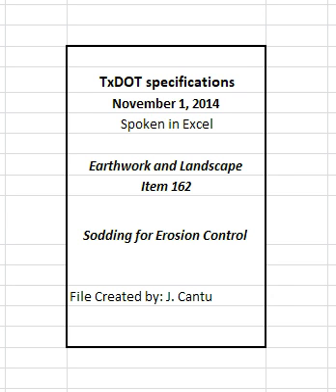3.3 Straw or hay mulch. Apply straw or hay mulch for spot sodding and mulch sodding uniformly over the area as shown on the plans. Apply straw mulch at 2 to 2.5 tons per acre. Apply hay mulch at 1.5 to 2 tons per acre. Use a tacking method over the mulched area.